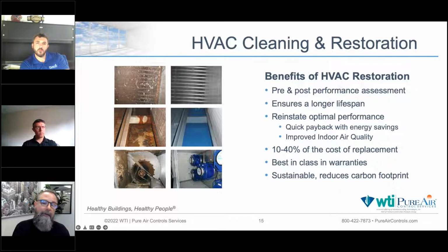Do we need to replace some dampers? Do we need to do more than just cleaning it and perhaps painting it? Or it could include retrofitting it, like the bottom set of pictures there, with a brand new fan wall or fan array, which helps to build redundancy into the system. So if one fan should fail, the other fans in the array will ramp up and you never lose the unit. The unit never goes down. These types of things are going to slide that restoration cost around.